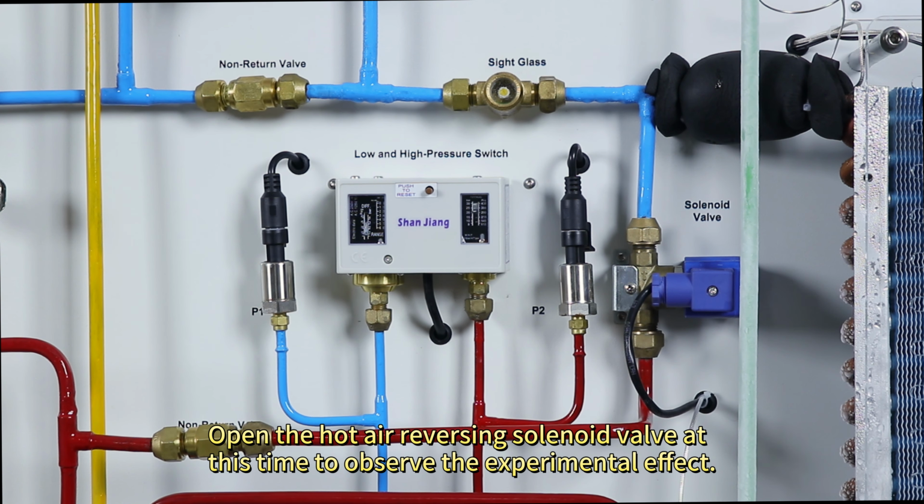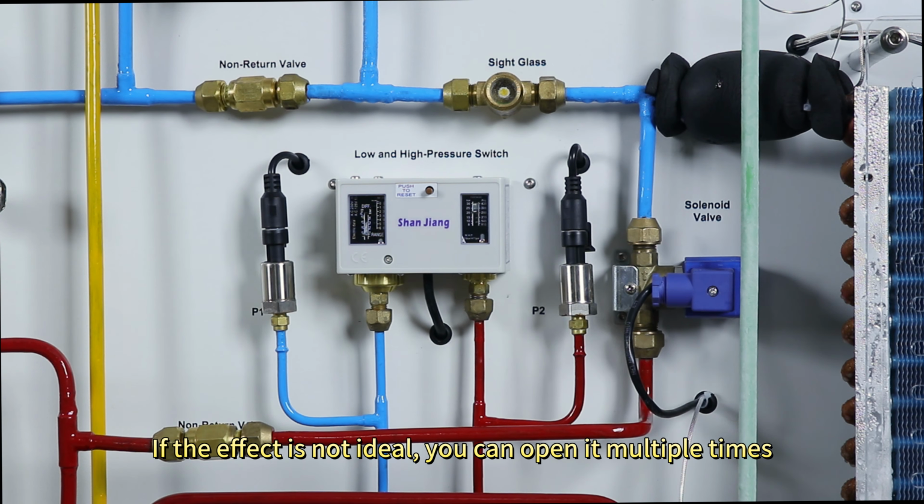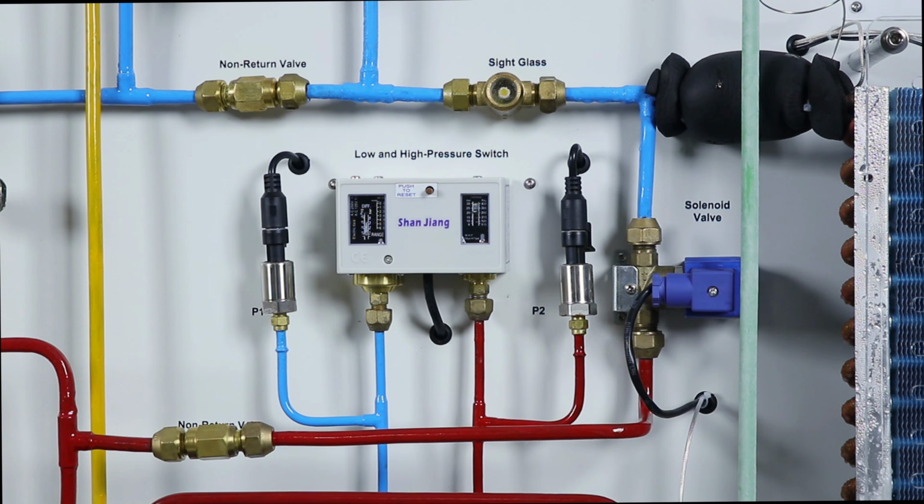Open the hot air reversing solenoid valve at this time to observe the experimental effect. If the effect is not ideal, you can open it multiple times. But you need to wait until the solenoid valve is automatically closed before opening it a second time.